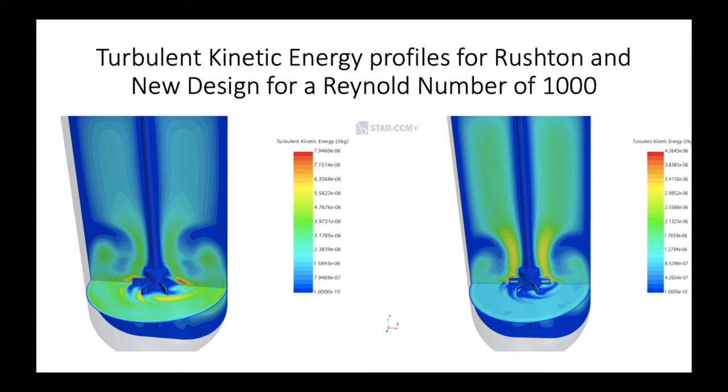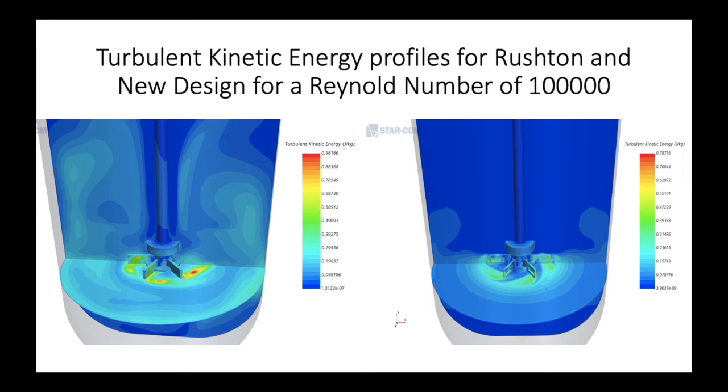The new design geometry lowers the amount of power supplied by the impeller. As a direct consequence, the energy transmitted to the fluid will also be lower. For a Reynolds number of 100,000, the same behavior can be observed, in which the highest values are obtained on the edge of the impeller blades. Nevertheless, further discussion in relation to the energy pattern shown previously cannot be made, as the total physical time employed for the simulation was significantly lower, due to the lower time step specification.